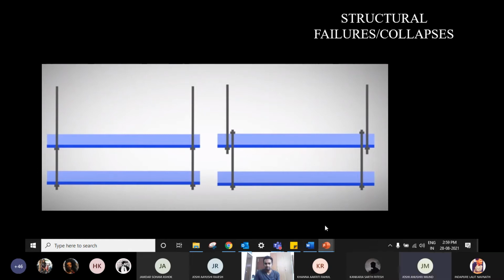Maybe the joint at the top. So in the second case, the way the lower walkway is hung onto the upper walkway, in the first scenario the bracing or the joint happens below the walkway, but here the entire weight of the lower walkway could be pulling down the upper one.